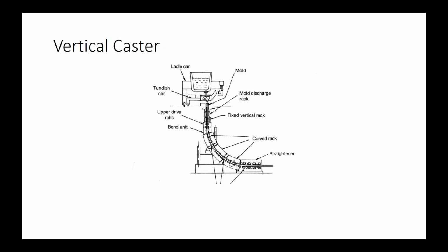The mold has just below it a whole series of cooling jets and water jackets, going all the way down this string. You see there are cooling jackets and rollers that allow the product to move easily in a channel for proper movement. Now, you can cut it off at any place. You can run this straight vertical. You can turn it like this. So there's various ways of handling this.